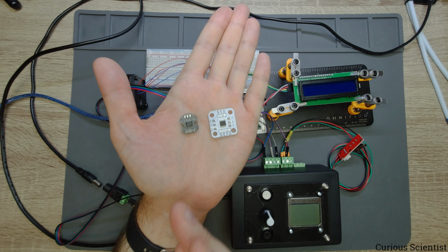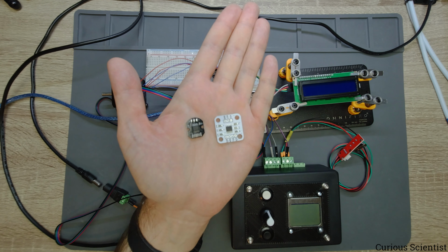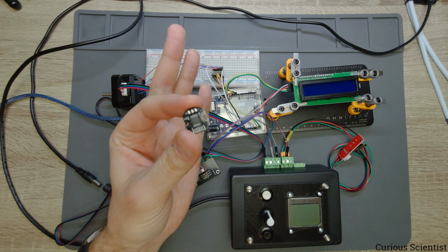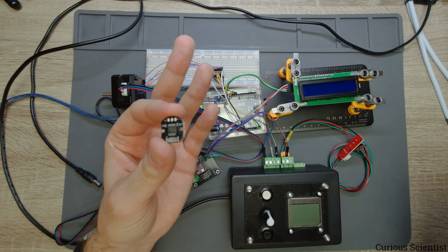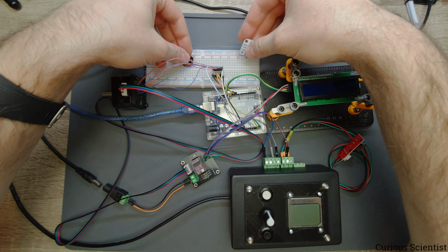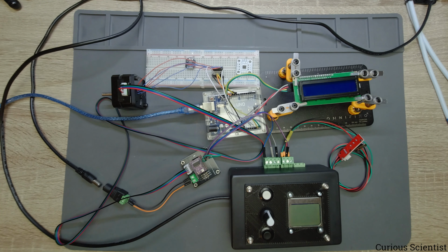The advantage of this is that if you use standardized SPI, then based on the chip select pin of a certain unit like this, you can put several on the same SPI bus and then just select the corresponding detector or sensor based on which chip select pin is brought low.